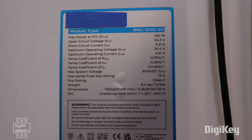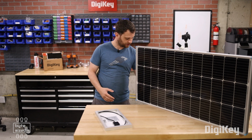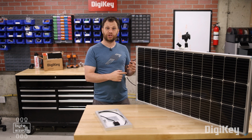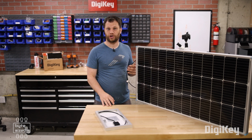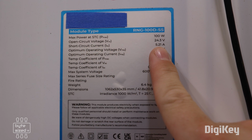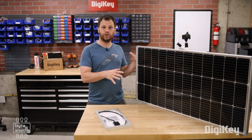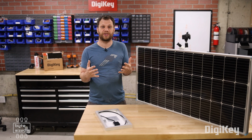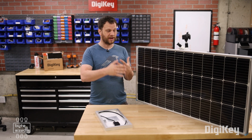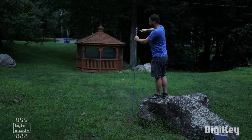The second piece of information I want to know about my panel is the short circuit current. If I take the positive and negative terminal of the solar panel and I connect them together, the current that I measure running through the wire is the short circuit current. In my case, that short circuit current is 5.2 amps. Now obviously these numbers aren't true if I have the solar panel indoors like this. These values are what the panel would produce under standard test conditions. But in the real world, these numbers will be different depending on the amount of sunlight, how many clouds there are in the sky, the temperature, and a whole bunch of other factors.